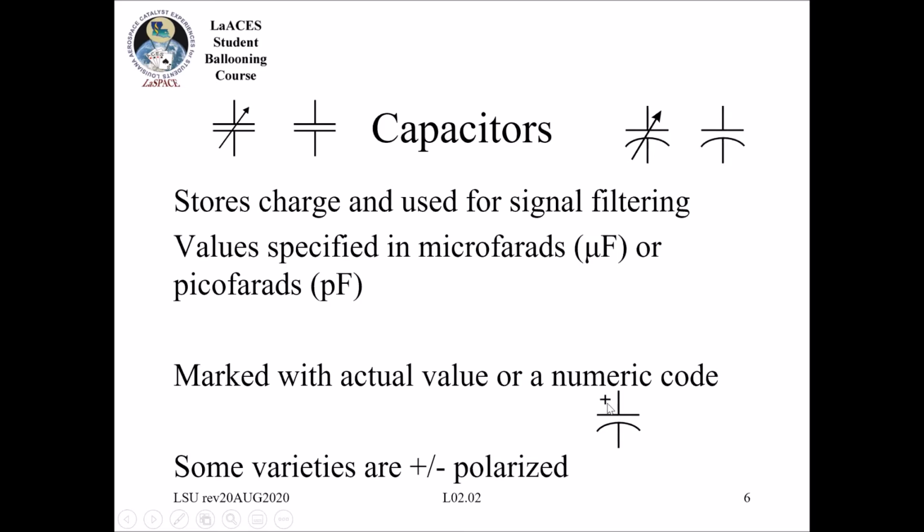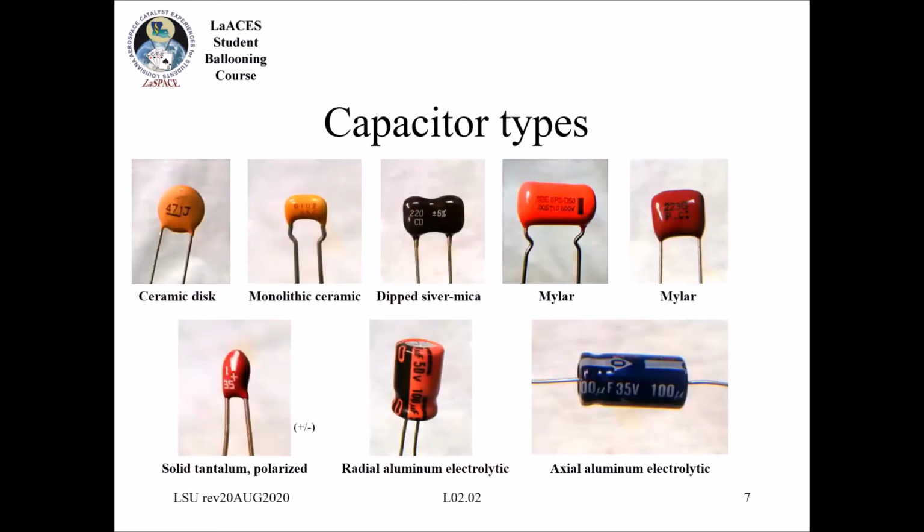And hopefully on your board, if you were to do a board layout or your schematic, you make sure to indicate that these things are polarized in your schematic, and you indicate the positive direction. And this means that whenever you plug this in, you should always put the positive lead with the positive voltage on the board, and then the other side should be towards the negative direction, typically, or ground. You'll see that. But not all capacitors are created equal, nor are they all polarized. So some of them are not.